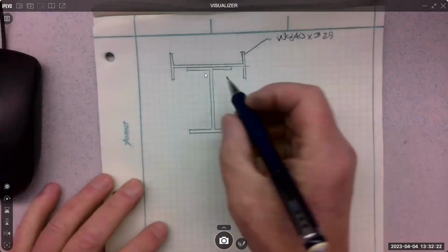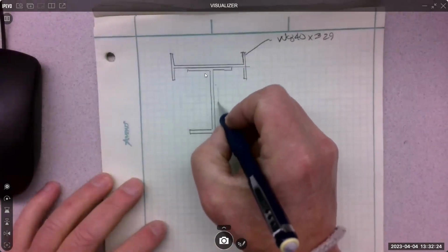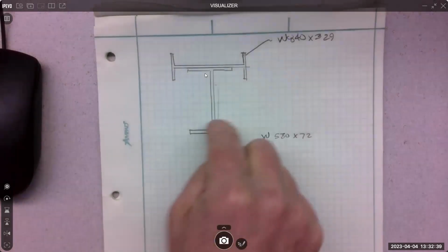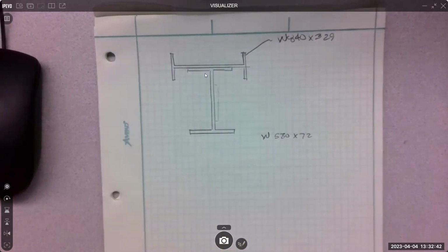Especially, I think I showed you guys this. I'm gonna do it really light, but like reinforcing the web with some steel plates. The next time you get next to one of those big trailers, don't crash, but glance over at the structural member and you'll see a bunch of these plates welded to the main structural member. Well, that's because in a region, there was a high stress level, right? When they did the design. So instead of beefing up the entire trailer, let's just beef up where that stress concentration is, right? So that's what those plates are doing, is just stiffening regions of the beam.